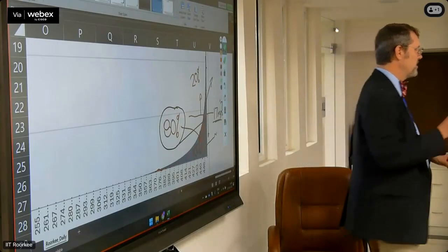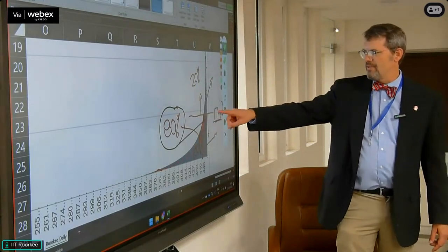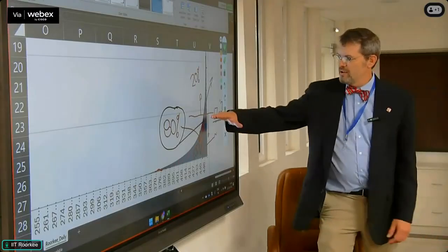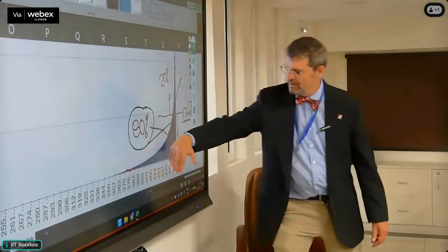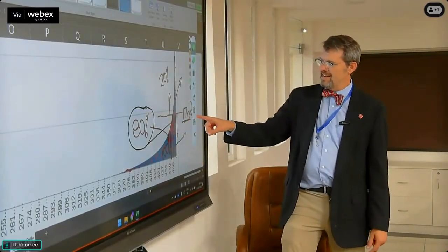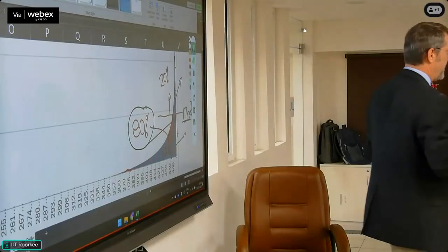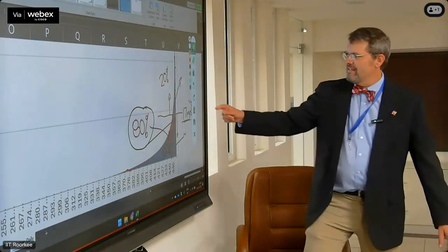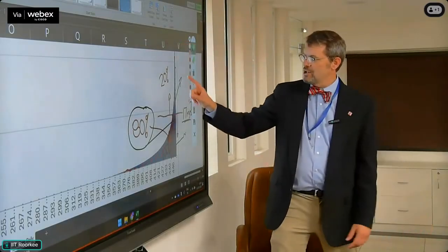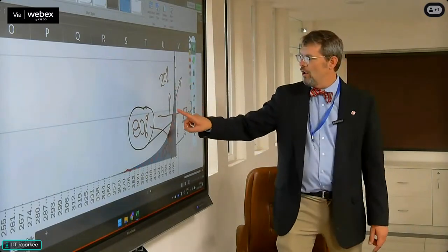Okay. So there is a rainfall depth. It's not 17, but right now I have it listed as 17, where if you looked at every storm that fell up to that value, plus all the other storms up to 17 millimeters, all of this equates to 80% of the rain that falls. And then everything above this line is bypass. And then the total amount of bypass would be 20% if you added all of this area.